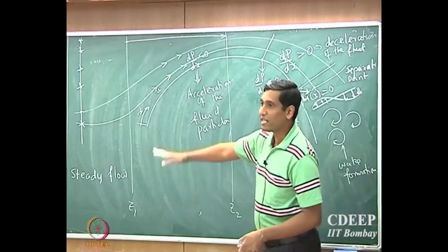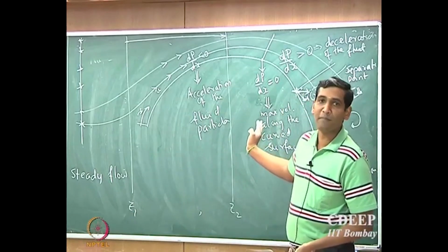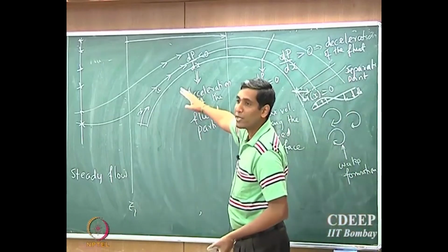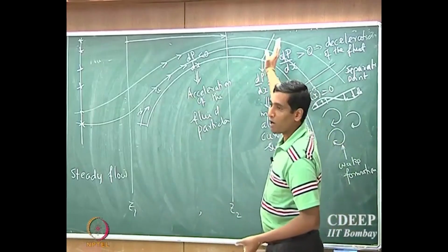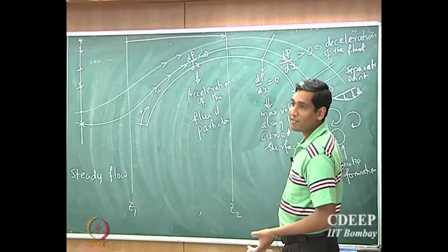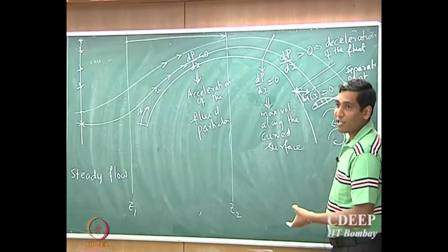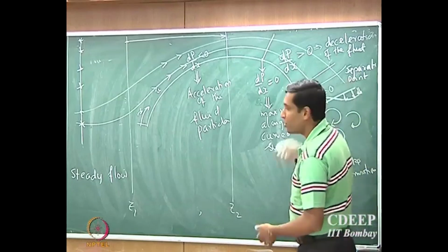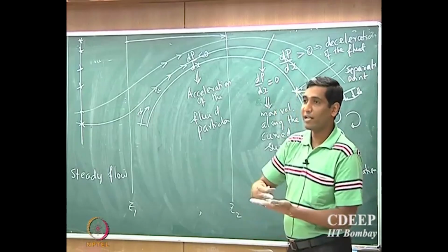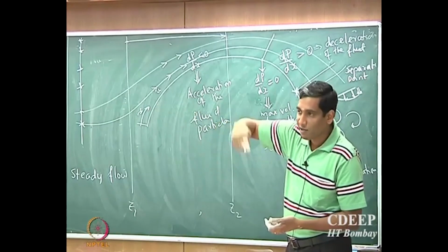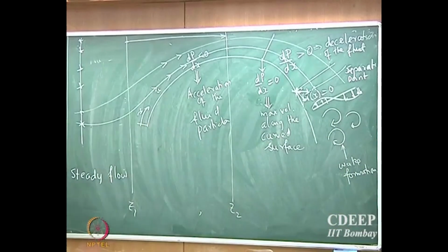Okay. So there is a series of interesting events that occur to the fluid particles flowing past the cylinder. It first experiences an acceleration, and then it's not able to sustain the acceleration, so the velocity goes to a maximum and starts falling down. There's an adverse pressure gradient in order to catch up with the rest of the fluid stream, and it's not able to manage it, and therefore the velocity comes to 0, and so it leaves the surface and starts circulating in the cylinder. Okay. So that's exactly what happens in this location here.